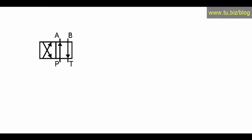Let's put the letters. The letters represent the ports. P for pressure, T for tank, A and B. So this is where the pump flow is coming in. P is connected to port A and B is connected to T back to the reservoir. When the valve is in the normal position, this is the schematic that we're looking at over here.